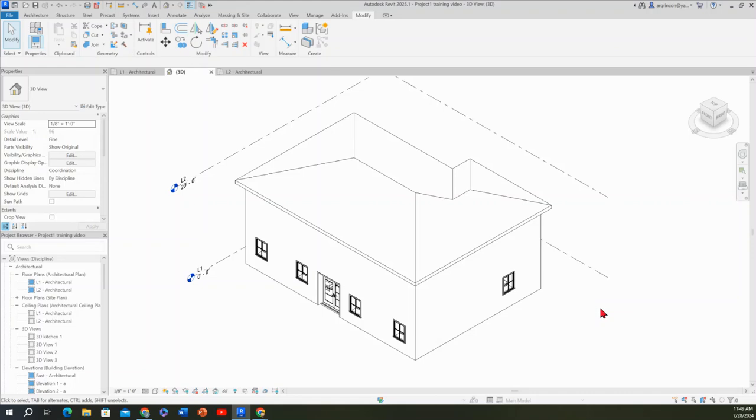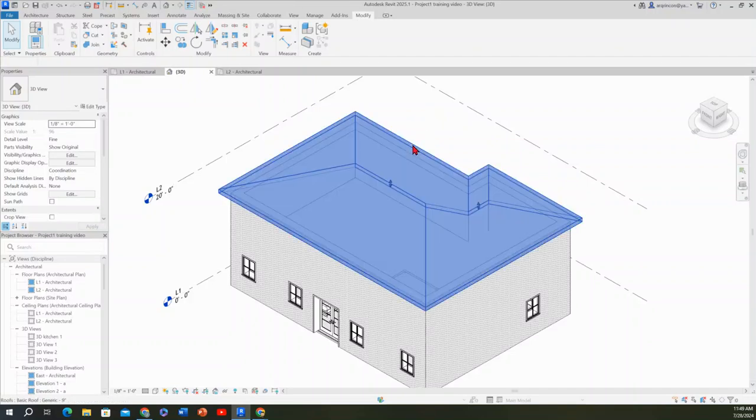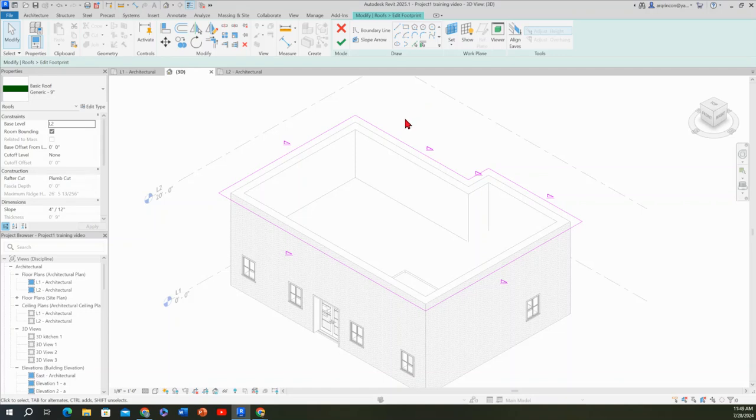Something else that we can do in Revit, trying to cover something else here. Let's say they don't like the project, they don't like the roof, right? So we can go and propose, selecting the roof, editing the footprint. And let's say we select those lines and tell Revit that this line will not define a slope. So you deactivate the slope, so no more triangle here, right?